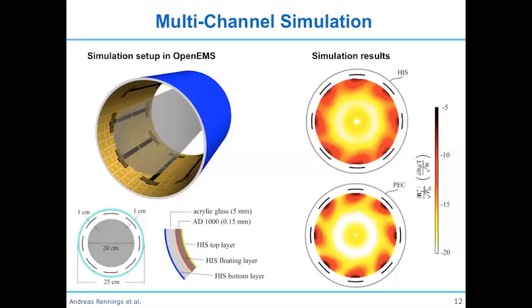Yeah, so that would be really the final result. Currently, we do also measure. We build it up, and currently we do also measurements with that multi-channel coil. One problem in the MRI scanner is this huge metal ground plane here. Initially, we just make it homogeneous to keep it simple. But before going to the scanner, we either need to make slits in that ground plane and solder big capacitors across the gaps in order to prevent the problem with the gradient fields.